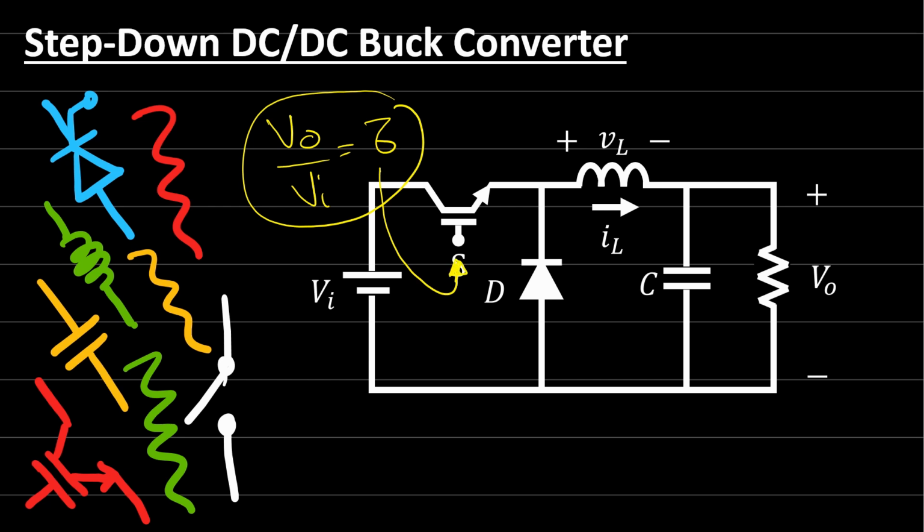Today we'll look at the constraints or limitations that make our converter work in a continuous conduction mode, which means these two switches store energy inside this inductor, and this inductor in such a way transfers the current to the output.